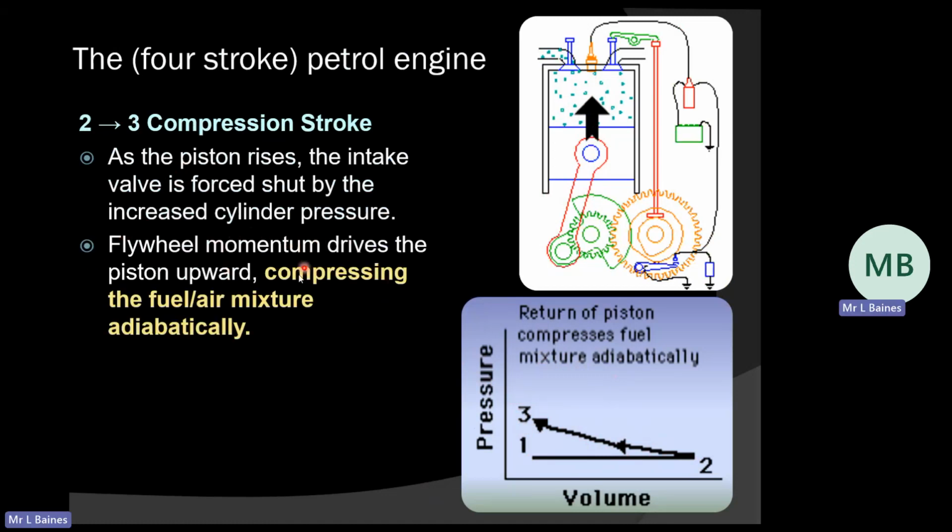This is where we have our flywheel helping us. Flywheel momentum drives that piston upwards, because we need to provide work to do that job. If we didn't have any energy to actually compress it, we've got to put some energy in, and that energy is given to us from a flywheel. So that compresses my fuel and air mixture adiabatically.